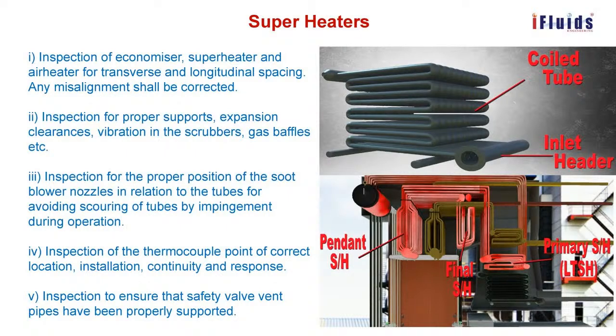All the example drawings have been given. Inspection for the proper position of the soot blower nozzles in relation to the tubes for avoiding scouring of tubes by impingement during operation. Inspection of the thermocouple points for correct location, installation, continuity and response. Inspection that safety valve pipes have been properly supported.